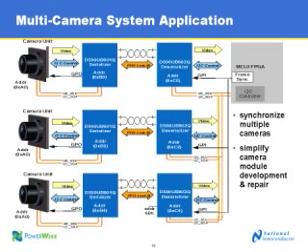Remember, it's continuous, so this frame sync pulse can happen at any time. It's not constrained by the data coming in. And then the frame sync is sent out of the serializer to the camera. All the cameras get the data at the same time from this initial frame sync pulse, and they can all align and then send their data back in relative synchronization.